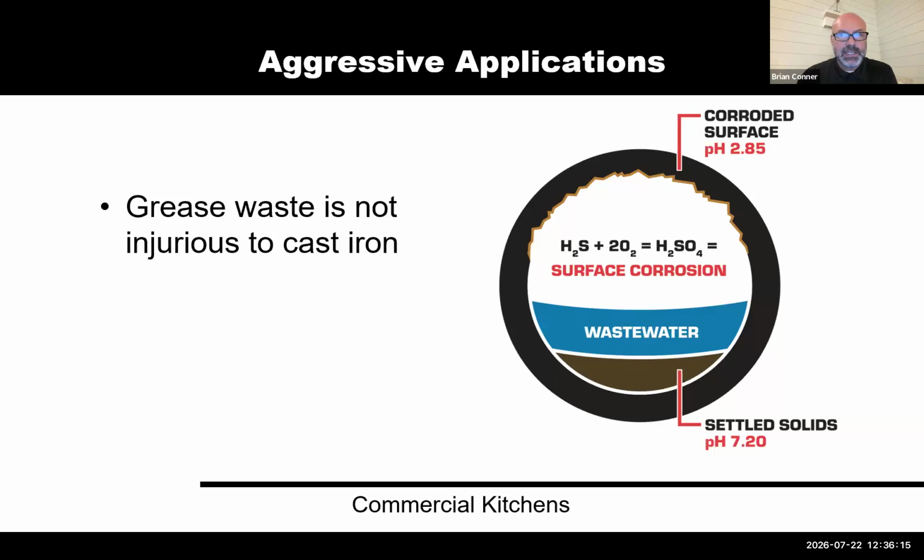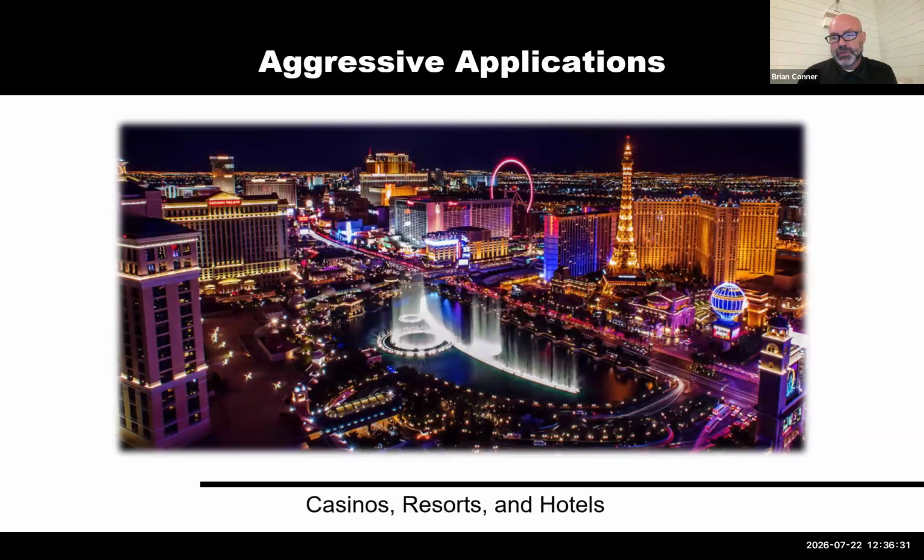If any of you have ever seen any degradation of cast iron pipe, it doesn't happen a lot. But when it does happen, it seems to manifest itself in this 12 o'clock region. And this is typically the culprit for that. So sewer gases are extremely hazardous to metallic piping when not vented properly, when solids are left behind off gas, when there's not a flushing system in place to make sure that the solids are not left behind.